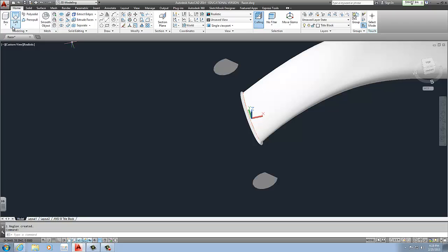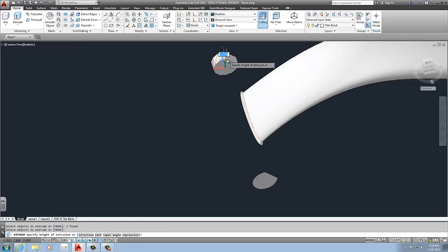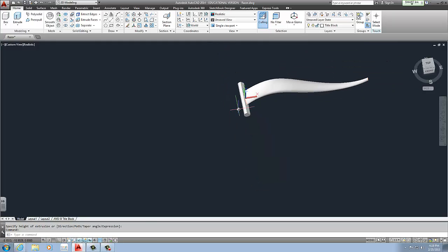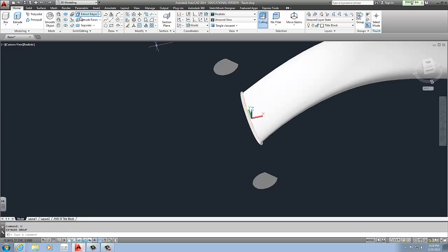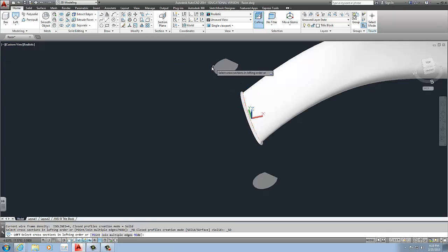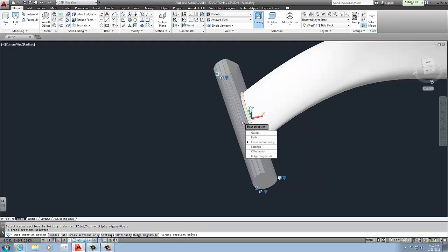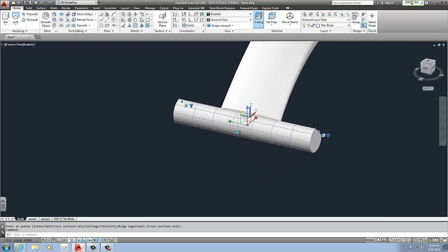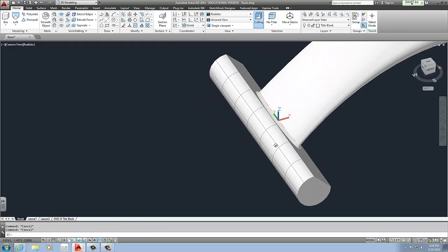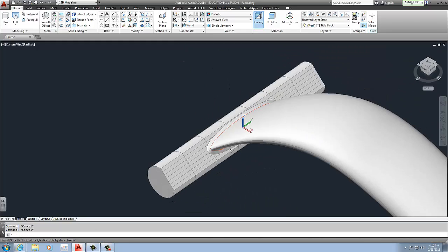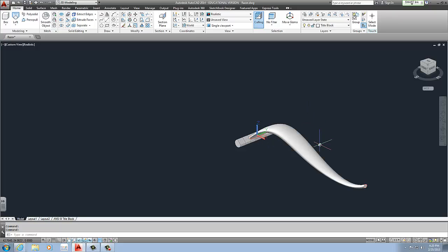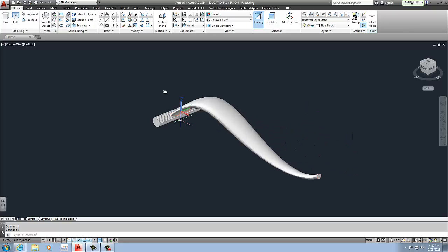One option is the simple option of extruding the part based on the distance of the other part. So by snapping onto it, it figures out the distance. The other way would be a loft, but we might not need to use that. Loft, you select that to that, and you click enter to accept it. The nice thing about loft is you can adjust these surfaces later on. This is actually a surface. That's creating the handle. Now, if you wanted to make it a little bit different and creative, that's also acceptable.